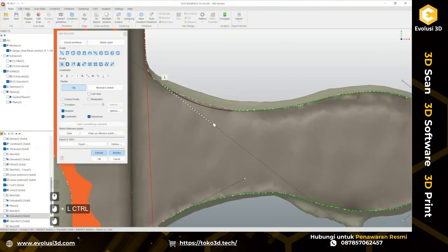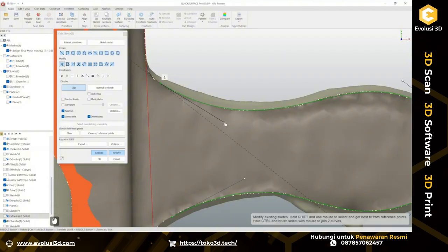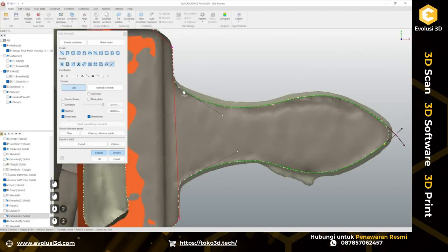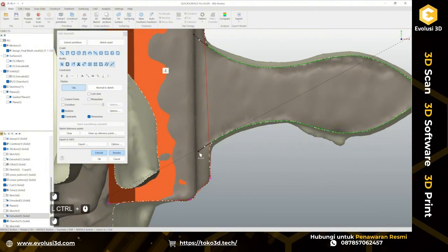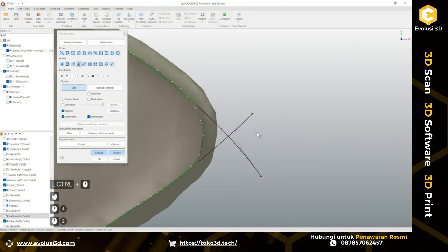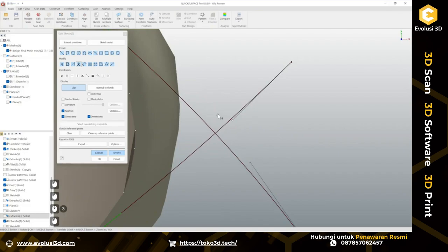Here as well, I want to snap it on 2 points. Okay, let's make it something like that. And after that, I can come over and extrapolate these curves to intersect them. Extrapolate in this direction. So I have complete intersection with my solid. So let's trim these endpoints.